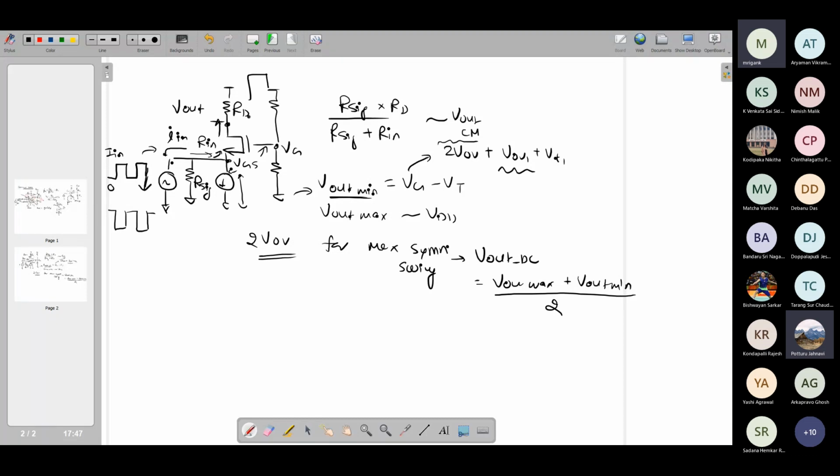Here we can see the two cases: in one case signal current is being supplied, in another case it is being sunk, and the behavior is different. That also tells you whether you want to use an NMOS input device or a PMOS input device. I can also make a common gate with a PMOS input device. There the scenario will be different, right?